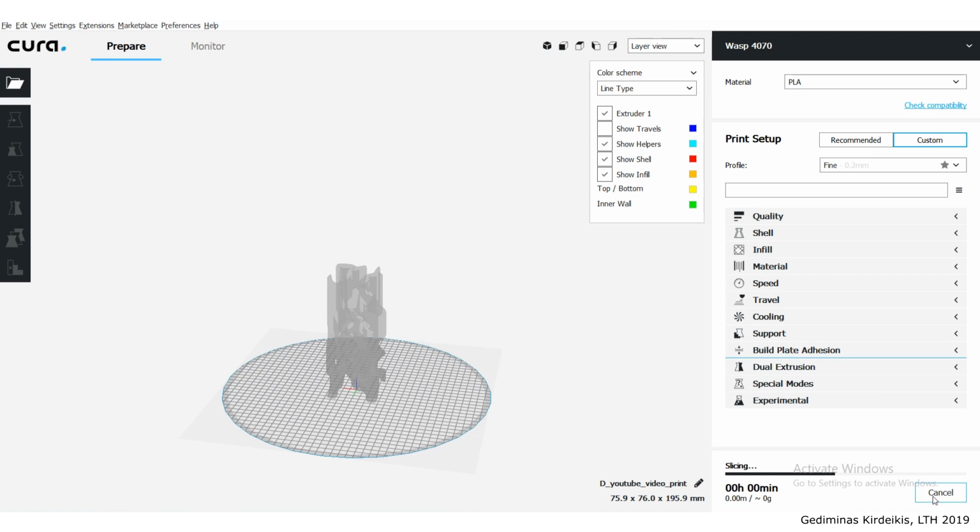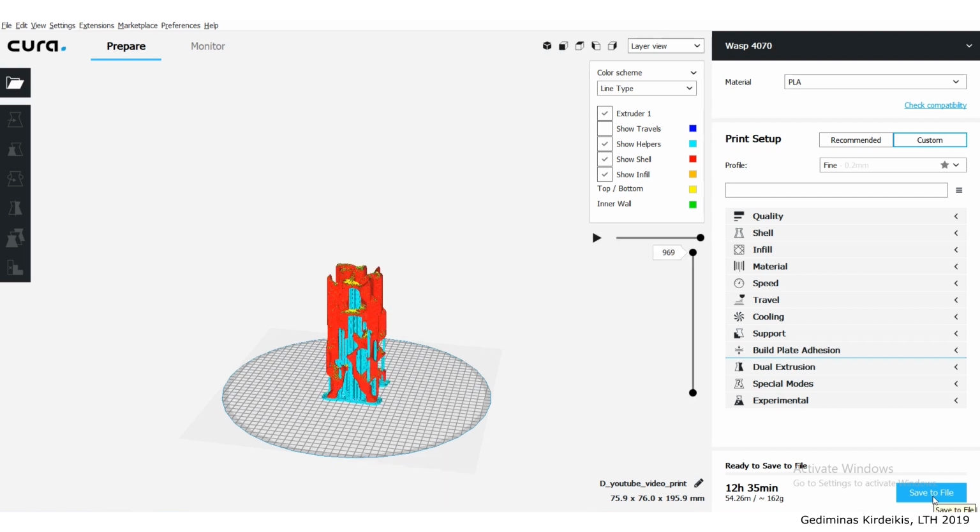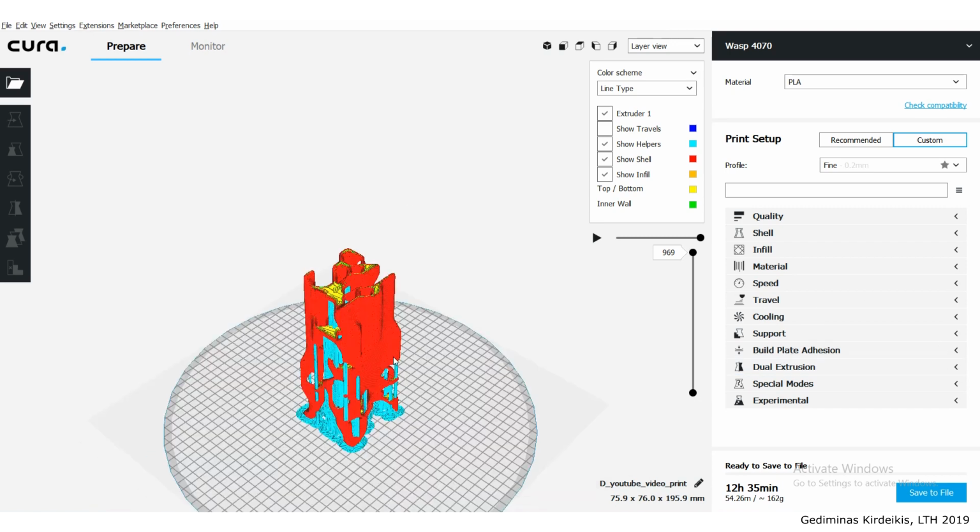So this machine can run a bit faster, like 90 millimeters per second, because its build plate is fixed and the only thing that's moving is the nozzle. So there's no additional vibration of the model since it's not running on a track or anything. So here, for the same quality that we would get with a Prusa i3 Mark III for an 18-hour print, here we can have the same quality in 12.5 hours, which is quite nice. Yeah, and that's basically it.